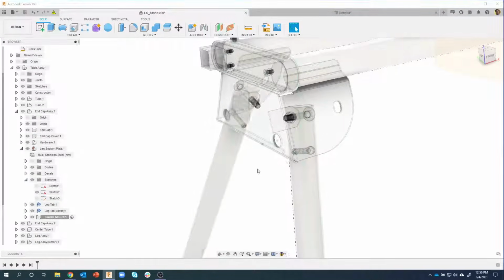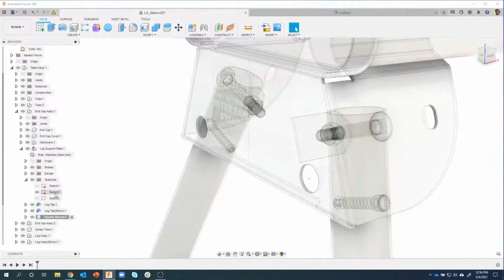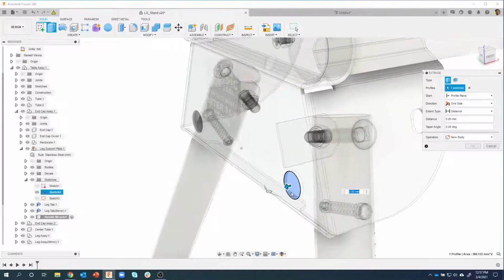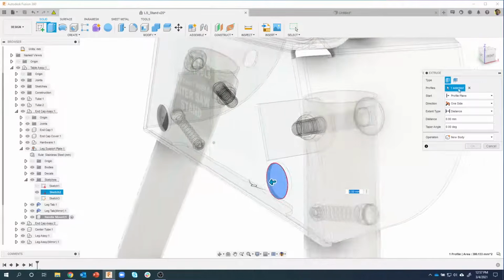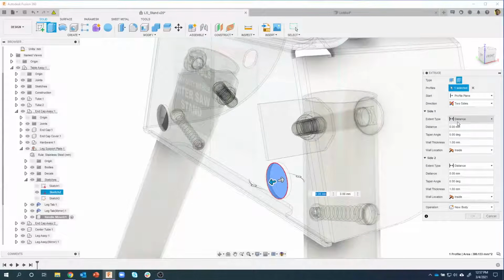turn on this existing sketch. Now we use this sketch to create this hole, so I'm just going ahead and turning that back on, and we're going to use that profile to extrude. I love this new command. You see me use it almost every single time, this thin extrude. Basically, we're going to create a small insert here. So check this out. I want it to go a certain distance one way and a certain distance the other way. So I'm going to say 2 sides.